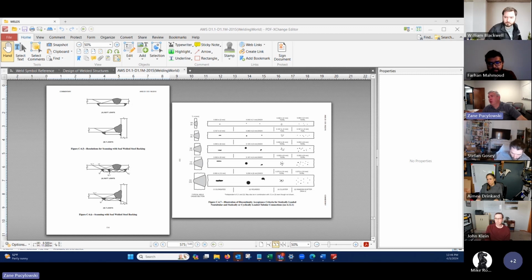What would you call out for not welding at the corners look like? A note that says no weld. If you want the hold back, you put that in the notes and you'll put a little dimension. You'll put in like 1/2 inch hold back, or you'll put that in the tail. 4-inch weld center, 1-inch hold back each end. Just if you can read it and understand it, they should be able to also.